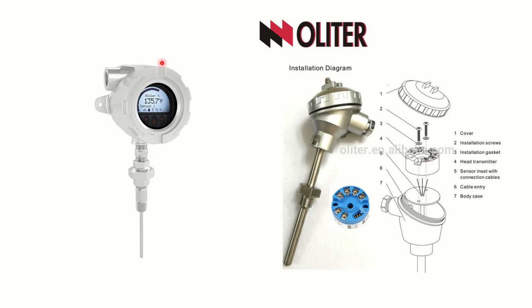If we take the example of immersion, they say that due to the huge installed base of 4 to 20 mA systems throughout the world, the HART protocol is one of the most popular industrial protocols today, because you can directly connect your transducer into this protocol. Now HART protocol has made a good transition protocol for users who wish to use the 4 to 20 milliampere signal current loop throughout, and they want to implement a smart protocol. That means you have the advantage of the smart protocol, as well as you can use this 4 to 20 milliampere standard signal. So all these things are possible with these HART sensors.